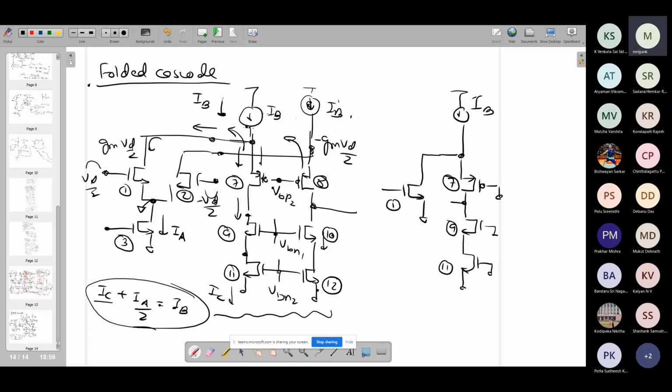So here what is happening, whatever small signal, if you are having Vd/2, so gm Vd/2, whatever small signal current is produced, if this is a good current source that doesn't change, the entire small signal current flows through this. And that's how we figured out what is the gain of this cascode stage, right? This folded cascode we studied earlier, we have studied exactly this thing earlier. We just figure out what is the small signal current going into this.